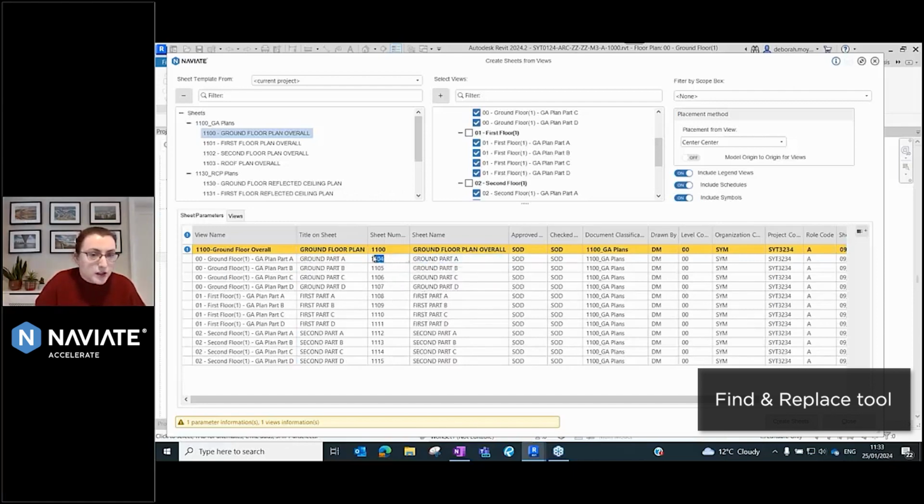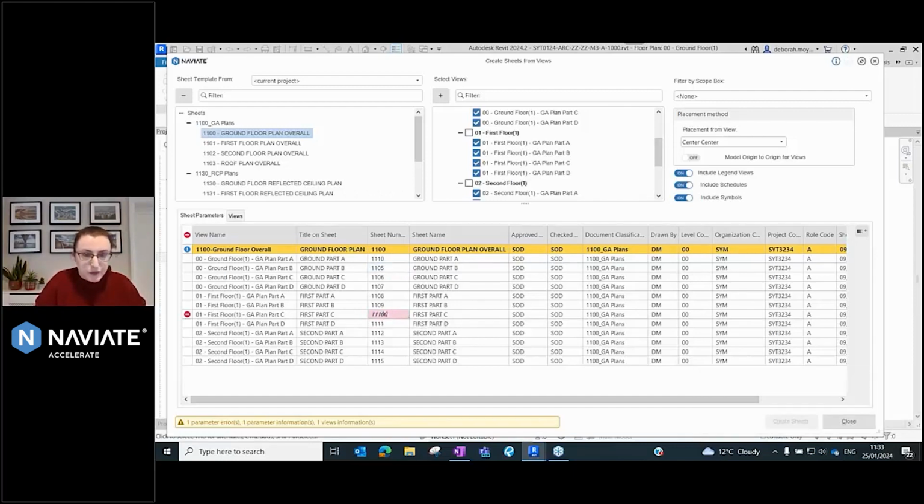I am going to set my sheet numbers as well. I want my series to start at, let's say, 1110. This is smart. It will prompt you if there are any duplicate numbers in there. So I can clear that warning before I go to my next step, which is using fill increment. So I've used fill increment, and these have all increased in value by 1. I have no duplicates. So all my sheets are numbered and all my sheets are named.